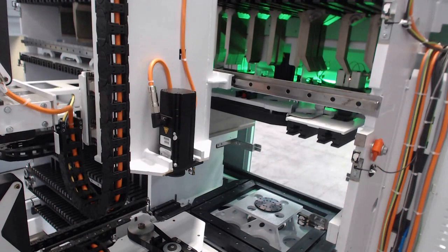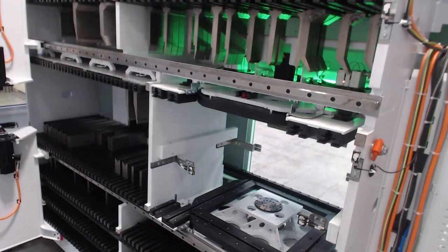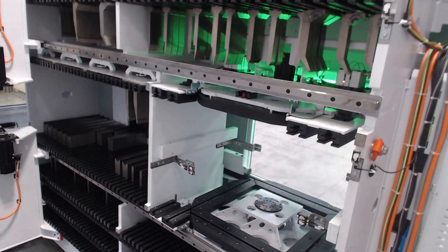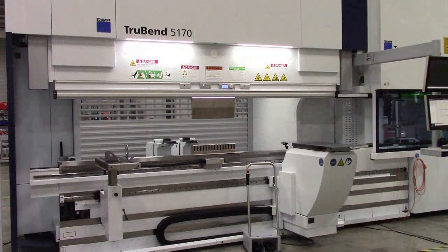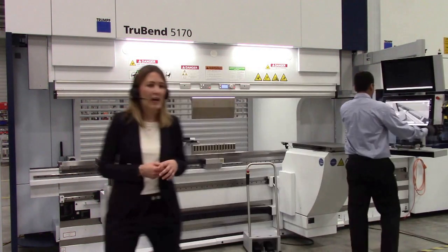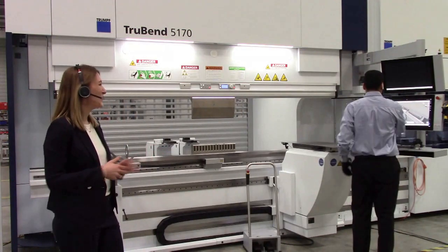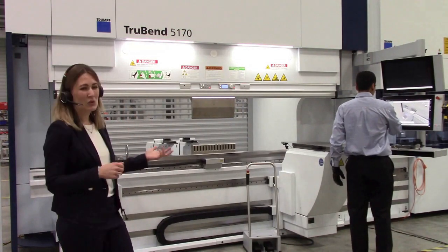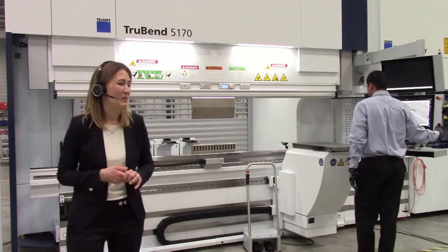They will also, for the next bending operation, pick up the new tools, excuse me, that we need. And yeah, now we already see that the next setup is done. The maximum tool size is a 500 tool. So this is what you're using here, and that is another option how you can optimize your non-productive times, because of course, when the toolmaster needs to grab less tools, then that makes the process more efficient.